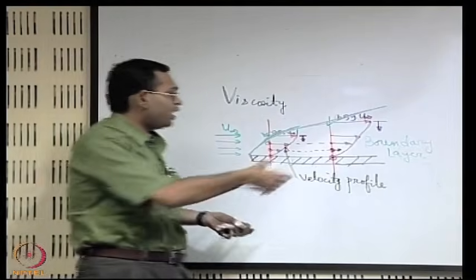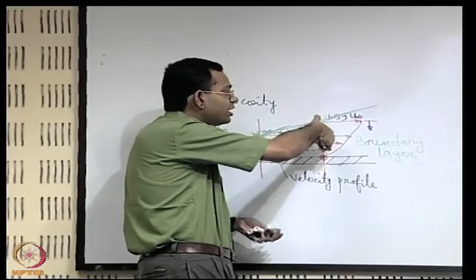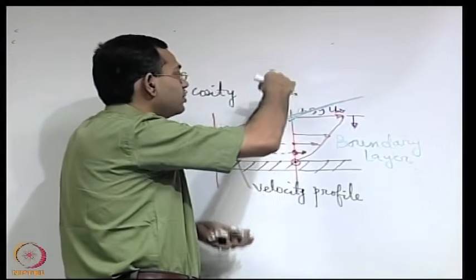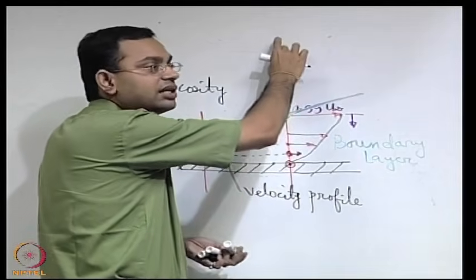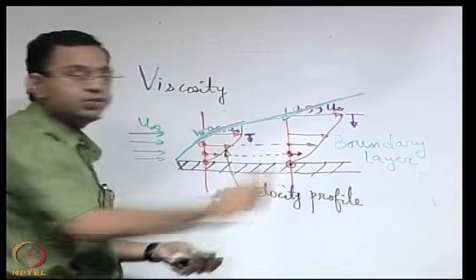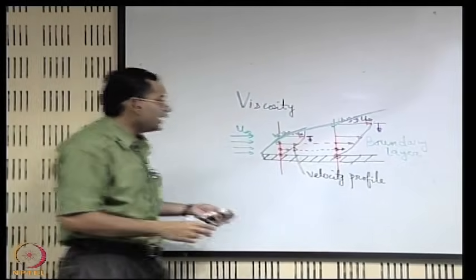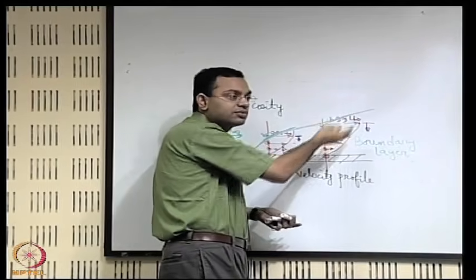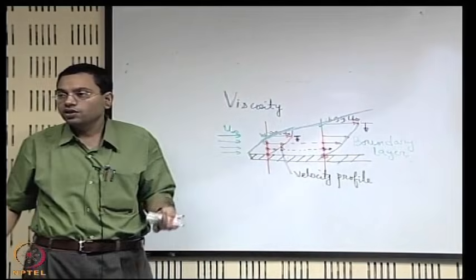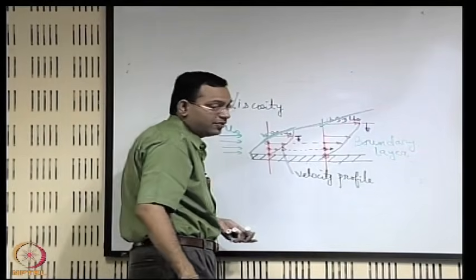So if you have a viscous flow analysis within this region, that may be good enough, coupled with an ideal flow analysis, or fluid flow analysis without viscosity, outside this region. So that is why conceptually this boundary layer is a very important concept. Not only that, most of the interesting physics in the flow takes place within this layer, and therefore it is very important to characterize this particular behavior.